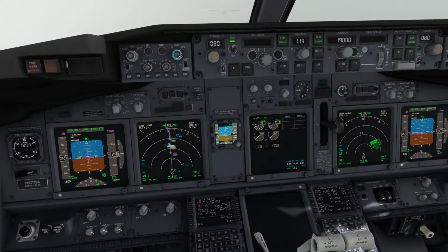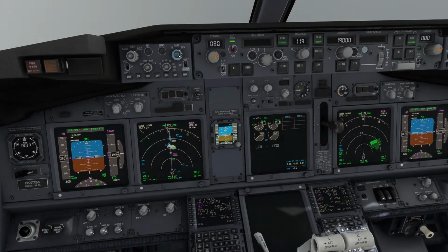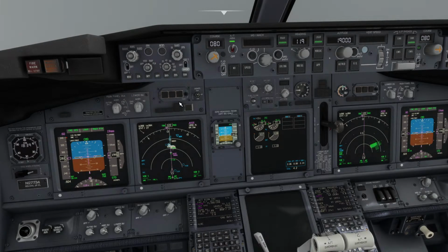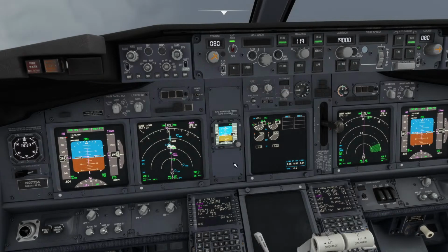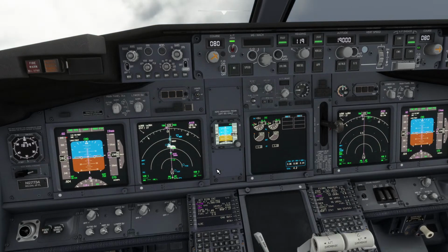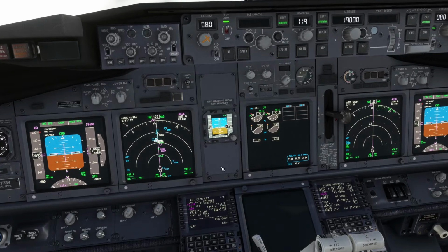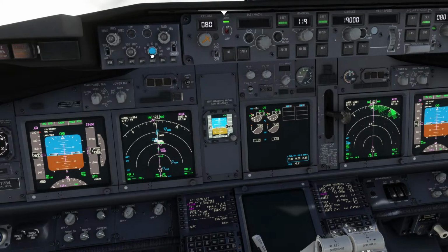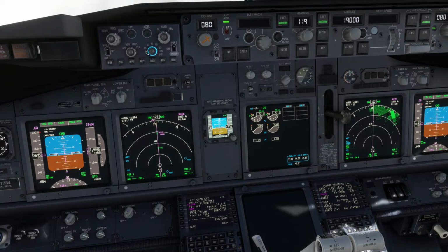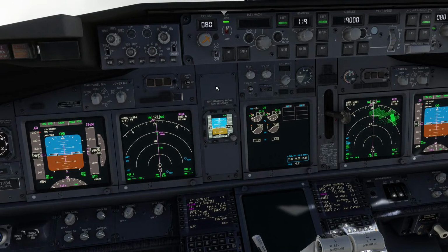We make sure everything is okay. So we talk to ATC. As we have a hydraulic system malfunction, the airplane is still flying, but I will declare to the ATC a pan-pan call. We don't really need assistance right now, but it's good for them to know we already lost one hydraulic system, the situation can deteriorate, and I will also ask them to let me know if there are any changes in the weather conditions, because again,